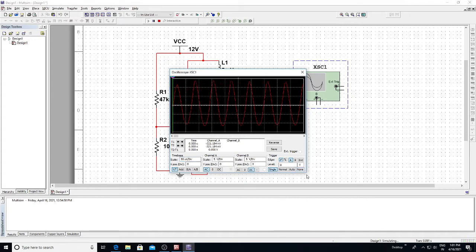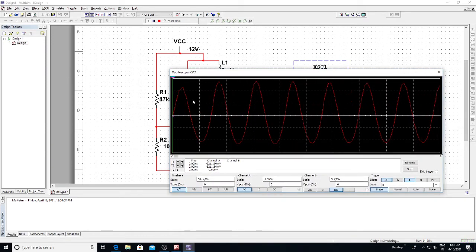Here you can find the time period as you found out for the previous case. Here you have a T1 time period. Place it near this end of the point and place this to the other end, and connect the T1. Now check, T2 minus T1 is 70.899 microsecond. So this is the practical time period which you are getting, and find the frequency, that is nothing but 1 divided by 70.899. Right. So you compare these values with the theoretical also.